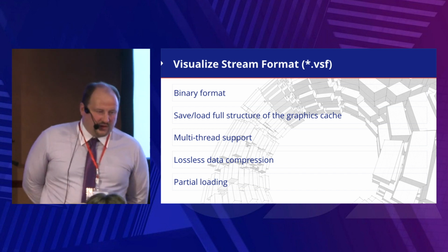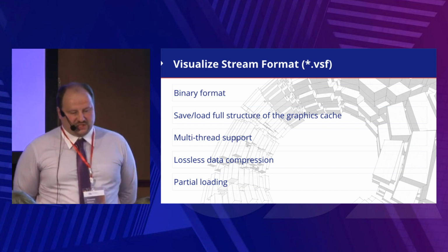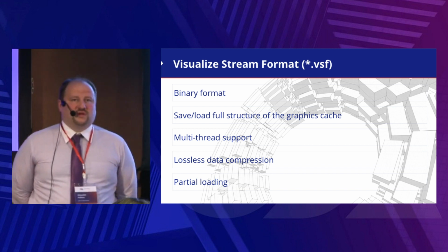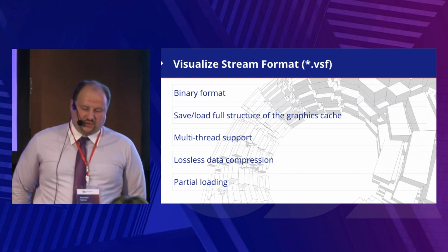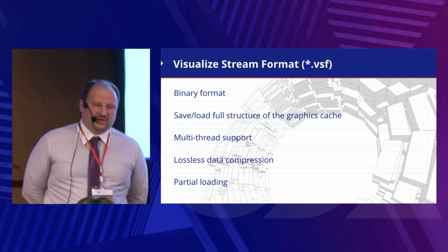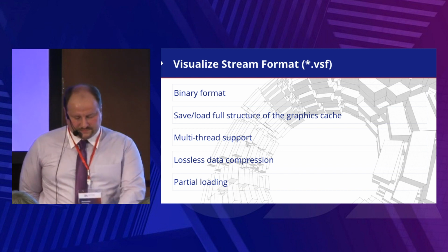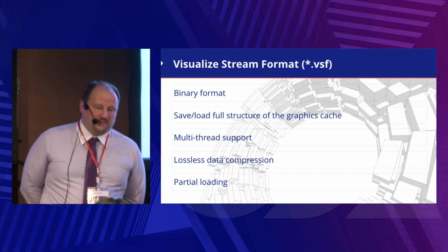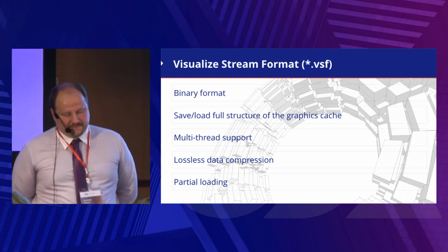For saving and loading data of the internal Visualize SDK graphics cache, Visualize SDK provides the Visualize stream format. Saving and loading data in this format is supported by the Visualize libraries. This is a binary format which allows loading and saving the full structure of the internal graphics cache, including all properties of the devices and views. This format supports multi-threading. This format includes lossless data compression, which allows us to make the final file smaller. And finally, this format supports partial loading.